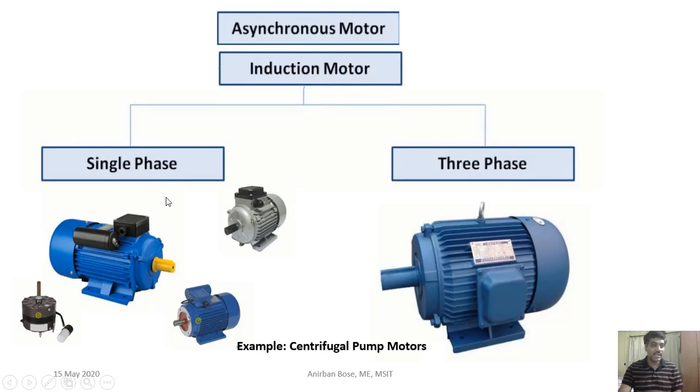Remember that in this case the rotor is rotating at a lower speed, and the stator field is rotating at a higher speed. In induction motors the speeds are different, stator and rotor having different speeds. That is why they are also called asynchronous motors.